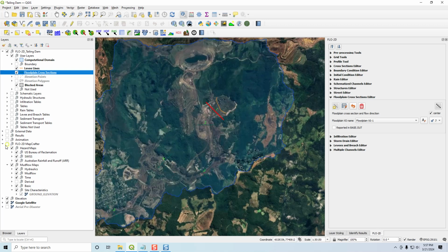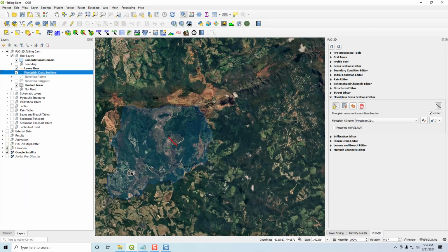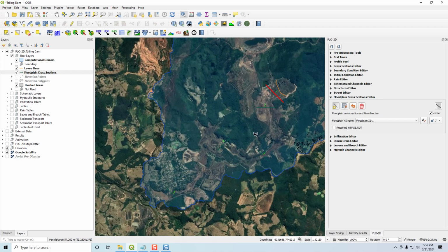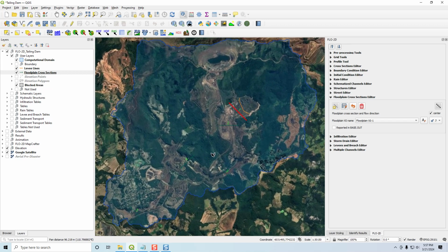Anyway, so that's how you use the layout tool, and that is basically it for the different types of Flow 2D maps that you can create for your projects, and the different types of time-dependent data and animation data that you can use to help you identify hazard zones and evacuation routes. And you can identify all those things. You can point sample any of those maps with important points. You can do profiles anywhere across this of any of those spots, and you can link those profiles back to the map. So it's just really excellent tool.